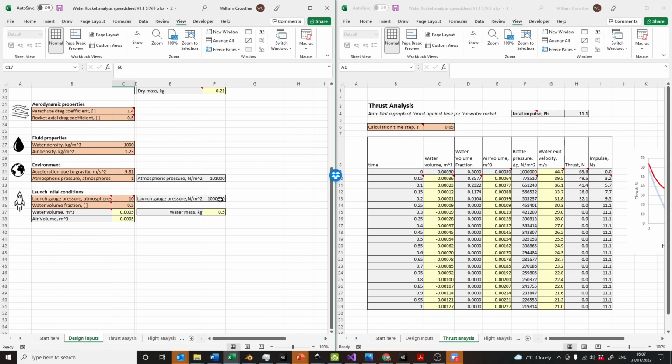But in the analysis, we convert that to newtons per meter squared, which is a big number here, which is very hard to read. Anyway, going back to the pressure, the pump we've got will pump it up to about 15 bar, but what we found is that anything more than about 10 bar and the rockets explode. So on launch day, we typically limit the launch pressure to 8 bar, so 8 atmospheres. That's still quite a lot of force inside your rocket.